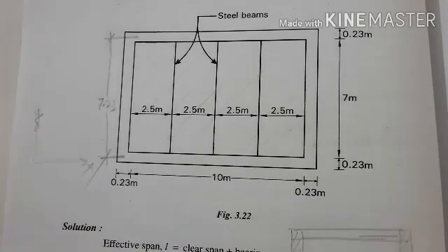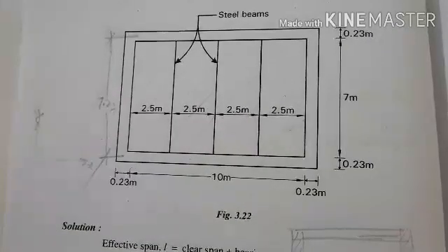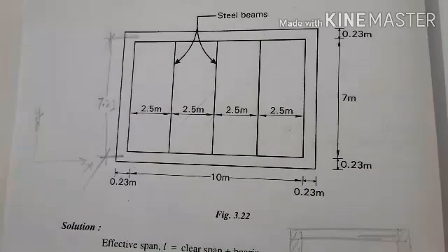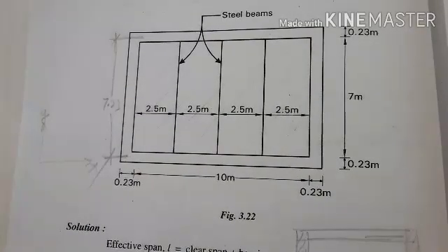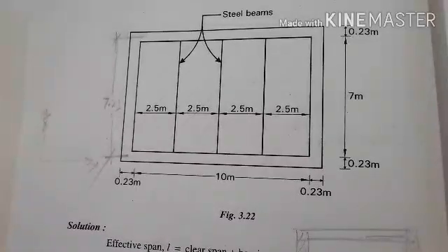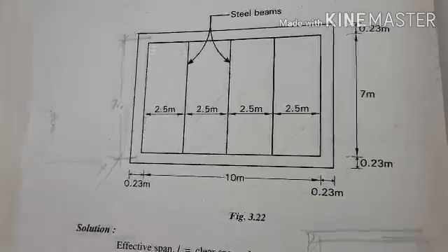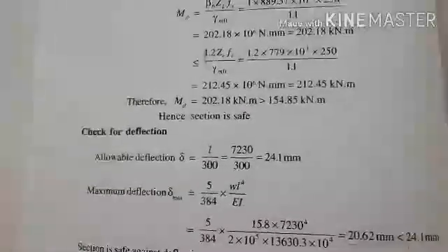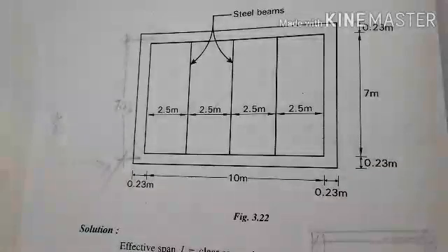The bending moment helps us calculate the section modulus, the plastic section modulus, and based on that section modulus we choose the section, since the section modulus indicates the strength of the member. Then we have to go on checking that chosen section. If it comes out safe in all the checks, hence the chosen section is safe and can be used effectively. So finally we have to make a comment like this.